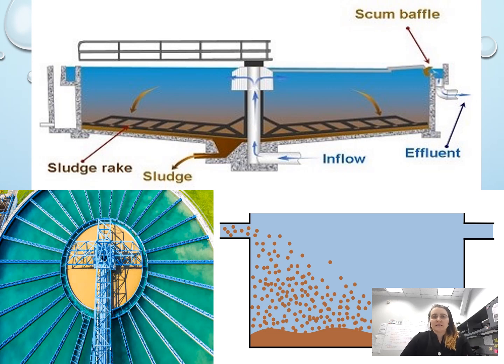Sedimentation basins can look very different. They can be rectangular in shape, they can be circular, they can be square, they can have that hopper shape, lots of different ways that they look. In the bottom right corner, you're going to see just a diagram of what settling looks like, right? They come in and there's that parabolic arc of solids starting to settle in the system.